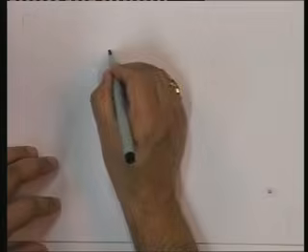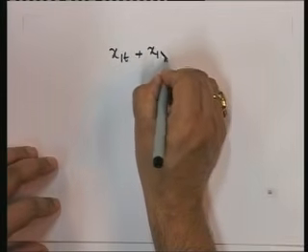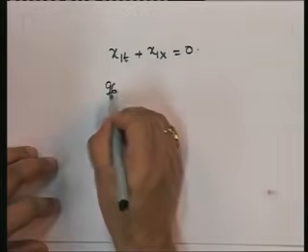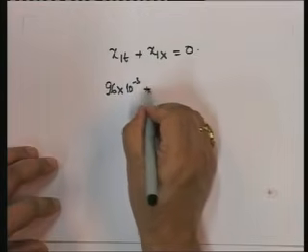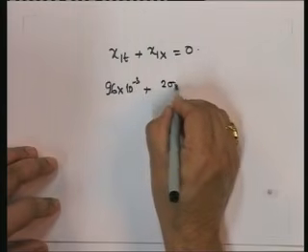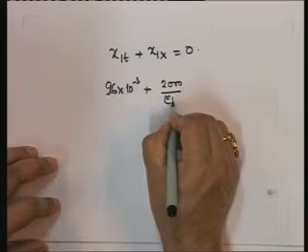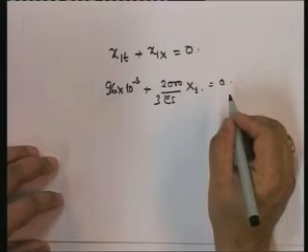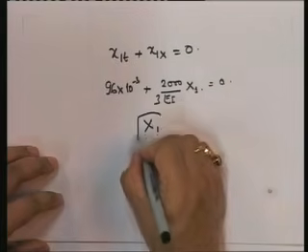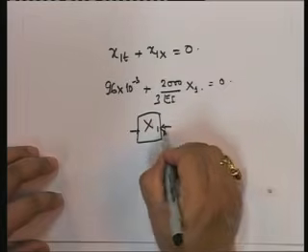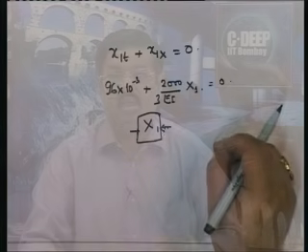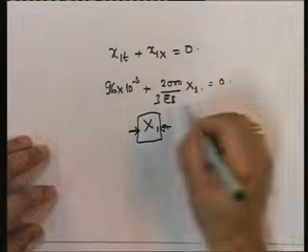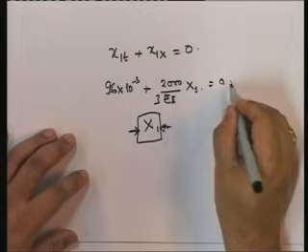I get x1 of t plus x1 of x equal to 0. x1 of t is 96 into 10 to the power of minus 5 meters, and this is 2000 upon 3 EI into x1, is equal to 0, and from that you can find out the value of x1. Once you find out the value of x1, it's a statically determinate structure, and you can find out the bending moment diagram. I am not going into that detail, because you need to put in the value of EI, etc., to actually solve for it.